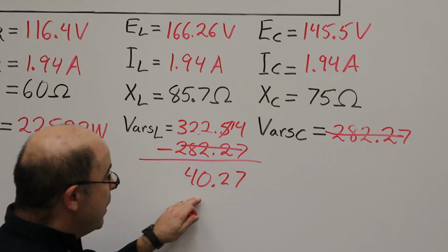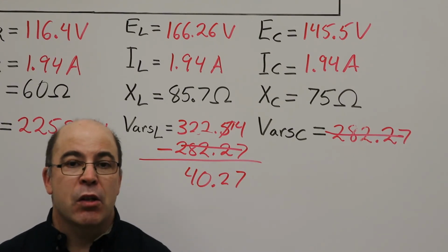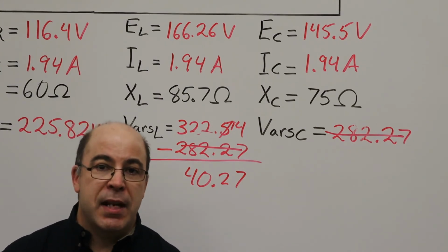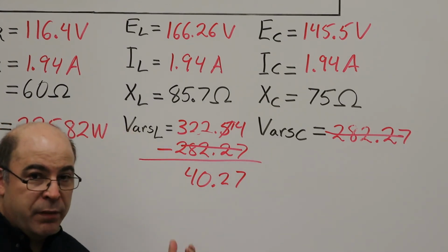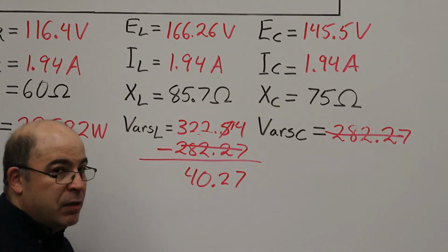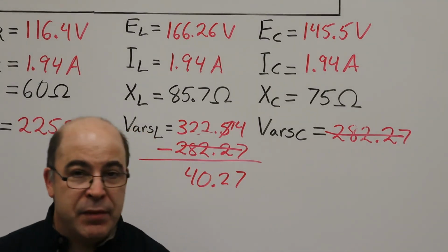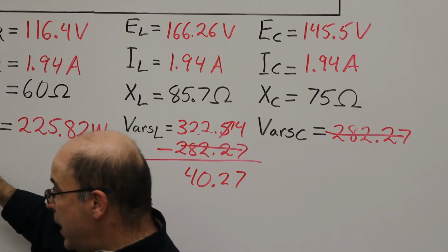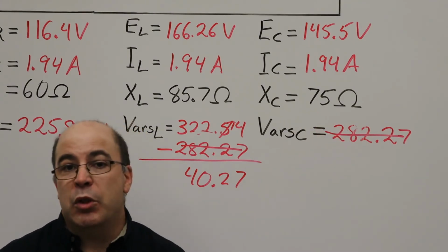This means then that I'm going to have the voltage leading the current, because this is a series circuit, but the voltage will be leading the current by 10.11 degrees. Now, in a textbook, if you've got more reactive power that is coming from an inductor, that gives you a lagging power factor. So what I'm going to have to do is, on the chart, write out that I have a lagging power factor, and we're going to display this when we start talking about the voltage and current relationships.